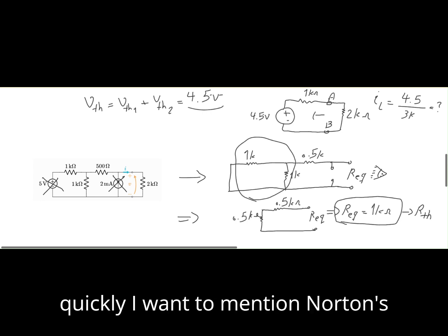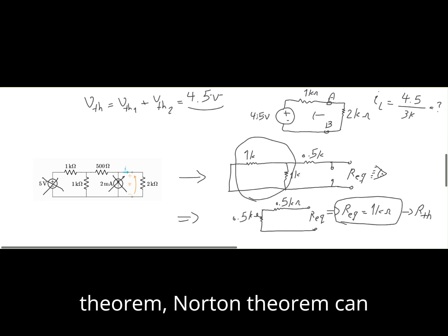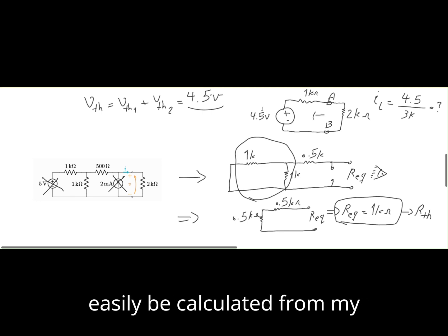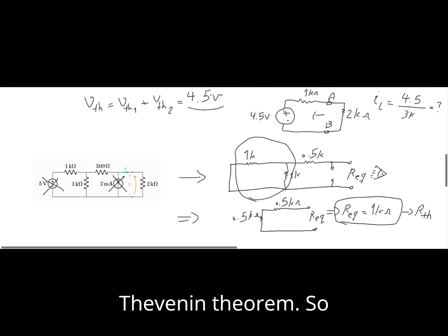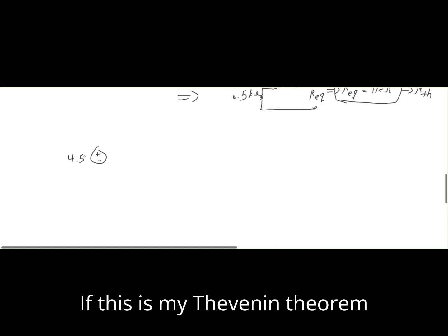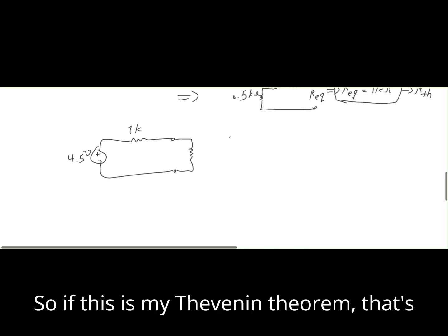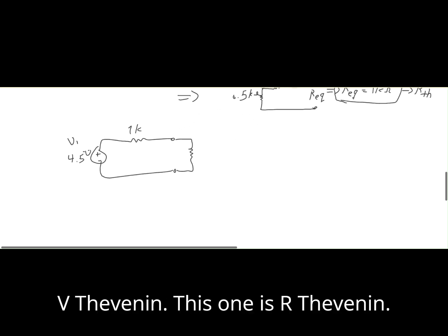So very quickly, I want to mention Norton's theorem. Once we calculate Thevenin's theorem, Norton's theorem can easily be calculated from it. Let me draw it again here. If this is my Thevenin equivalent, and over here I have my load, that's V Thevenin.